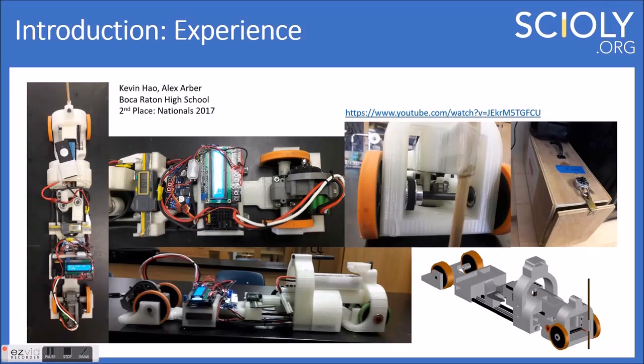We went to the orange 0.4 inch width, 2 7/8 inch diameter Bainbot wheels that have a 40A Shore durometer rating. We primarily switched to these wheels because we wanted something softer in the rear compared to the blue wheels that we had the previous year. But we also needed to keep them thinner.